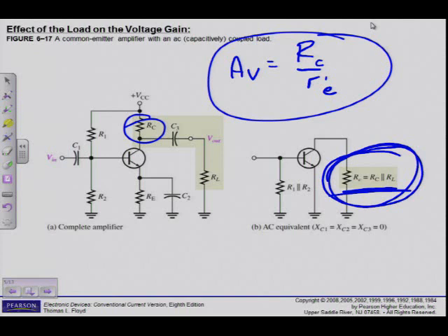So already I can see just by using a load resistor, in this case a 5 kilo ohm load resistor, it brought down the total output resistance to 833. But now can you imagine what is the impedance or the resistance of a normal speaker that we use on an amplifier? Do you know?